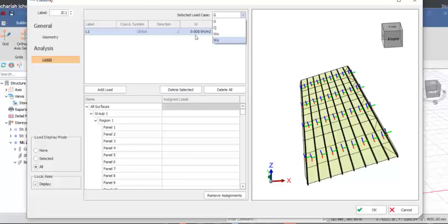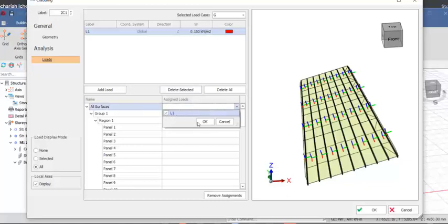But apart from that, you can use the basic wind speed in meters per second to actually apply the wind loading to the structure, which I will show you subsequently. Alright, so we haven't gotten this. Let's take our dead load for this to be 0.15 for this case. After having done that, you can come to this provision, select here, select this, and click on OK.